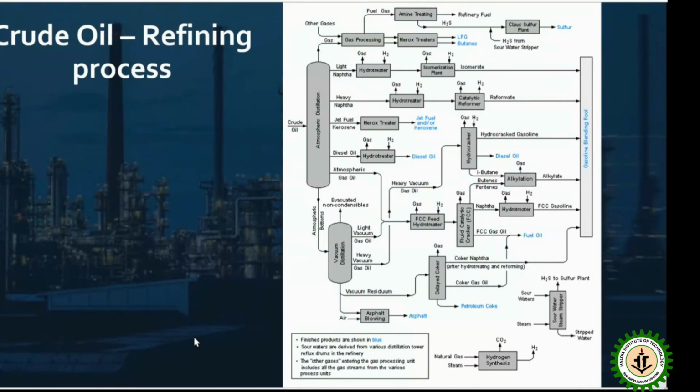Okay, sir. And what's the MOC for the distillation column, presently or previous one? Both. Presently, for the distillation column, an alloy is used having stainless steel, some amount of chromium and molybdenum, and LTCS, that is low temperature carbon steel. These are used to prepare the atmospheric distillation column. For the vacuum distillation column, it is always metal with less amount of carbon to make it vacuum proof.